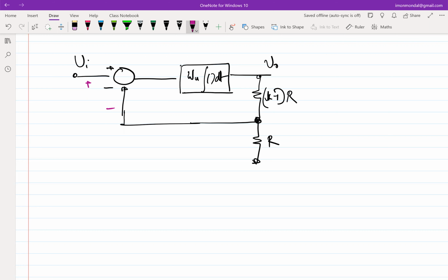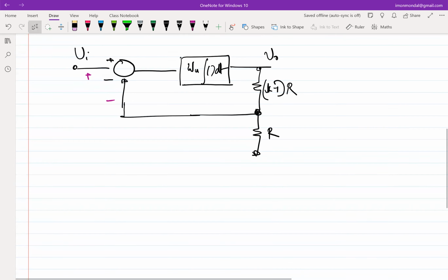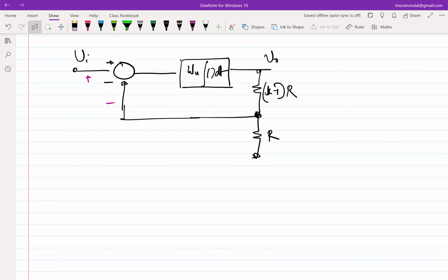Okay, and then we were moving into what happens if we have a non-zero frequency, because obviously you are not really always bothered about processing DC signals or step signals. You might also want to process sinusoidal or time varying signals, which means that we need to understand the characteristics of this loop when we apply sinusoids, because sinusoids are building blocks for all signals that we play with. Okay. So if the loop gain is infinite, 0 error voltage will lead to finite output.